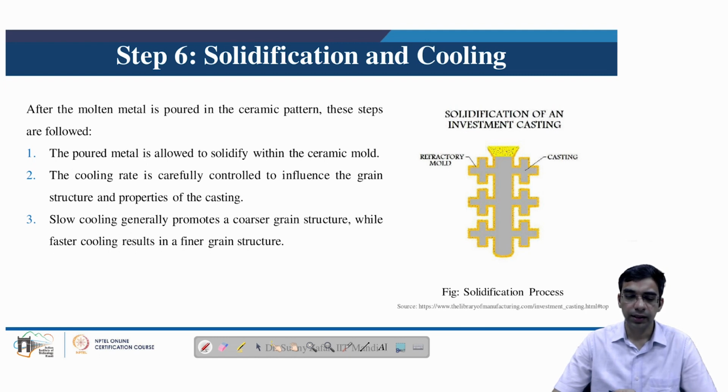In this case, it is important to note that the rate of cooling also influences the grain size, and to get finer grains, it is desired to cool at a faster rate, because slower cooling results in coarser grains which are not desired for enhanced mechanical properties.